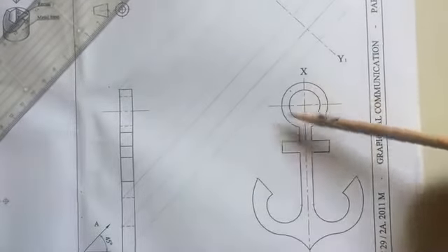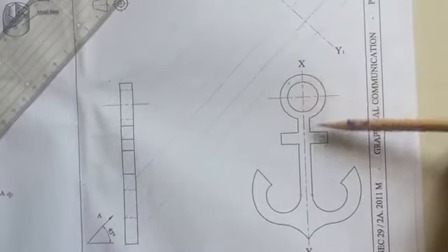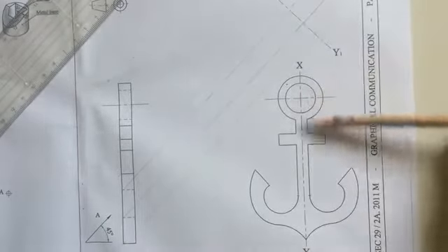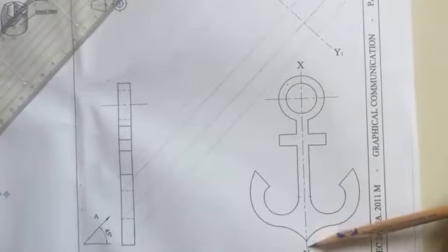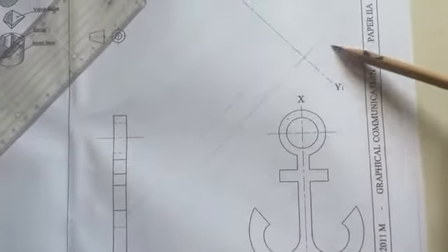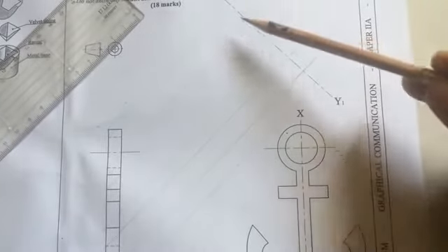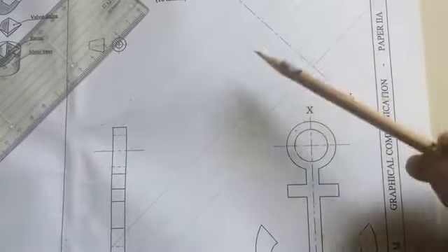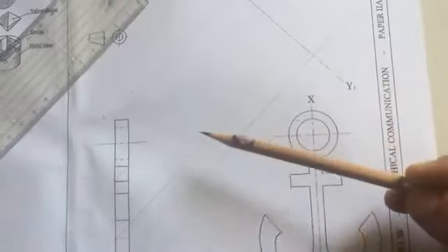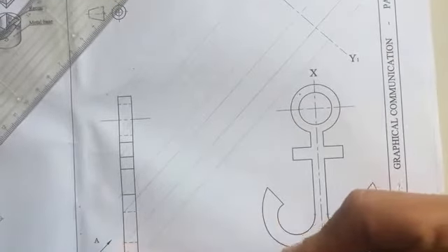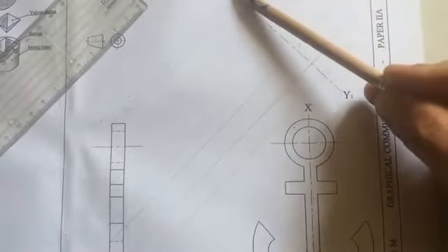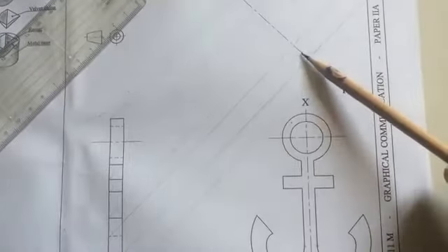So this phase gives me the XY line. So this question has the XY line here. That's the measuring line. You're going to use that to measure from. And then you've got another XY line in the auxiliary projection up here, which you're going to draw it on. So you take measurements from here and construct it here. This angle is always 90 degrees to the projection angle of the auxiliary view. So if it's 45 degrees projection lines, you get 45 degrees the other way to get perpendicular with the projection lines.